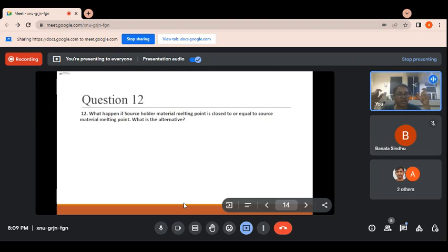Okay. And when it etches only in a particular direction, you can see in the TMAH process, when we fabricate the pressure sensor, that type of shape. We have to fabricate a diaphragm type. When we fabricate the pressure sensor, we have to etch the silicon wafer using the TMAH solution, and in a particular direction it etches out.